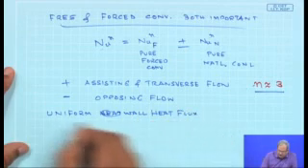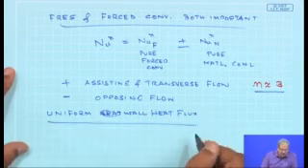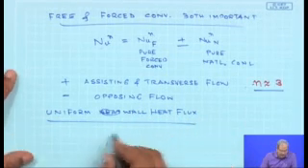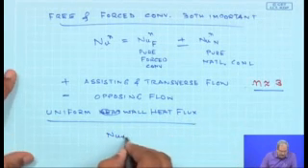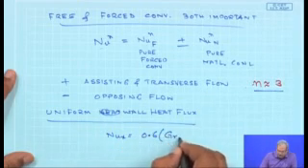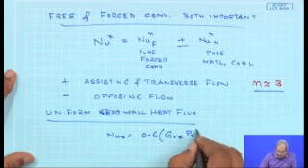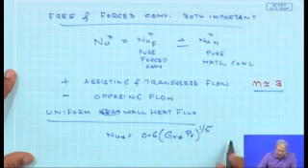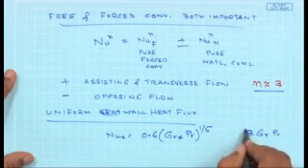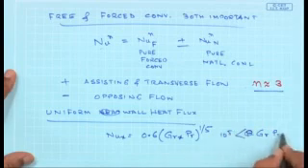This is another very common situation which you would obtain in the case of natural convection, where the Nusselt number is given by a relation: Grashof number times Prandtl number to the power 1 by 5, for some value of Grashof number times Prandtl number within 10 to the power 5 and 10 to the power 11.